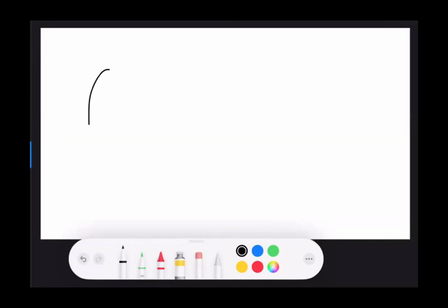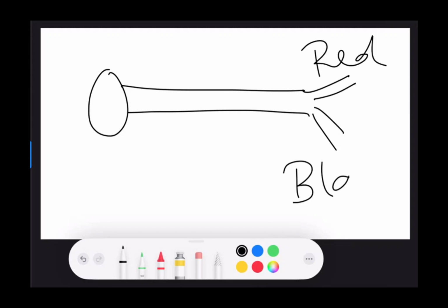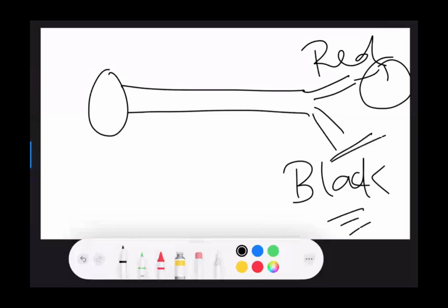You can see the CRO probe will have a circular type of thing, and this is the black cable which you see. On the other end of the CRO probe, you will have two banana clips, where one will be red and the other one will be black. The red one you will normally connect to the circuit where you want to obtain the output, and the black terminal you will normally connect to the ground terminal. And this part which goes and gets connected to the CRO is what we call the connector.